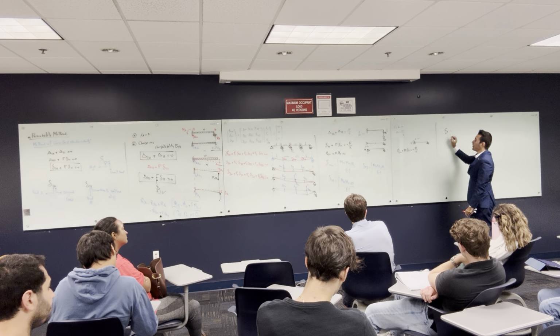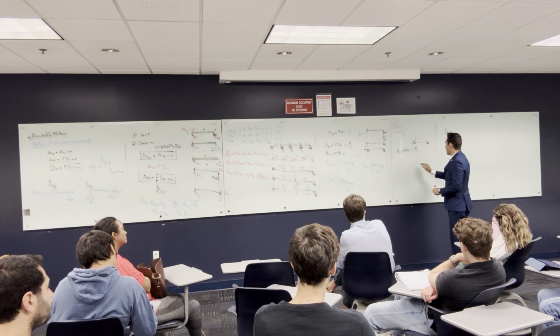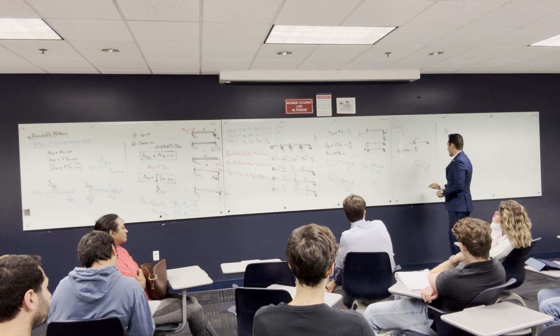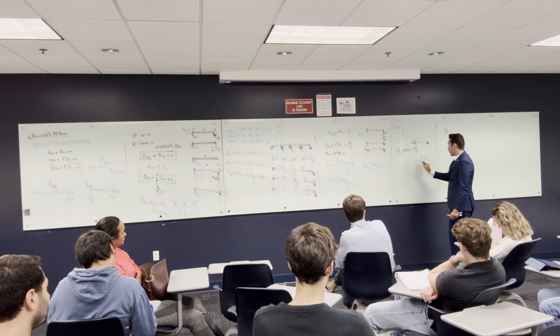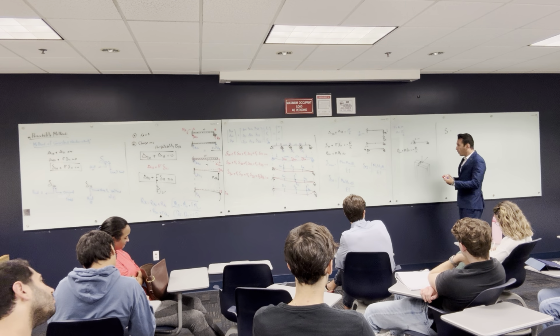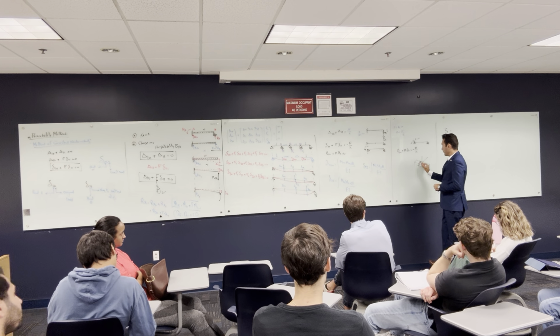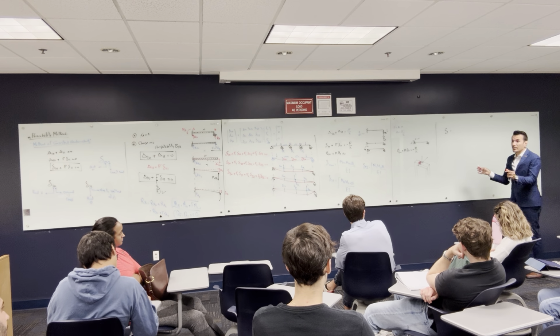This equation is because let's say you have a 3D frame, and this 3D frame is something, for example, like this, and has a bunch of load, like there's a load coming that way, and there's a load coming that way, and there's a bending one. So if you take a cross section here, this cross section is going to have all the loads that you can imagine. It's going to have shear that way, bending moment that way, bending moment that way, torsional. It's going to have everything, right? So that's a 3D frame.